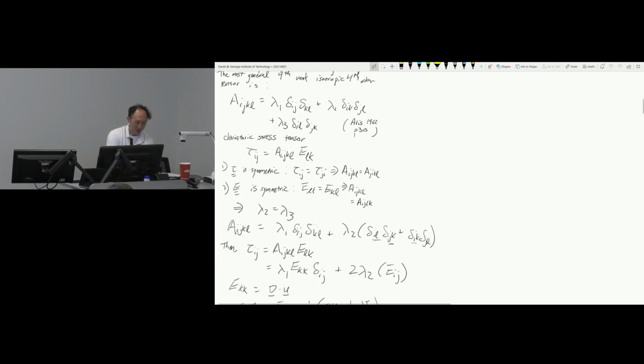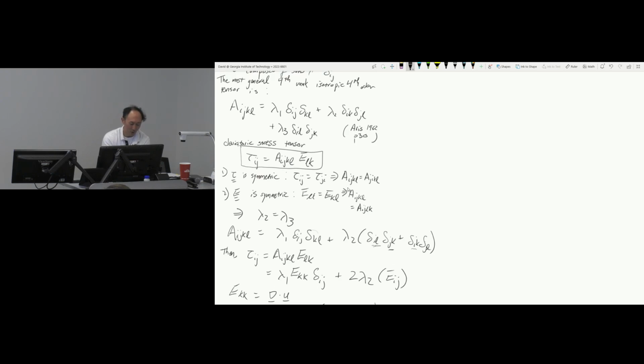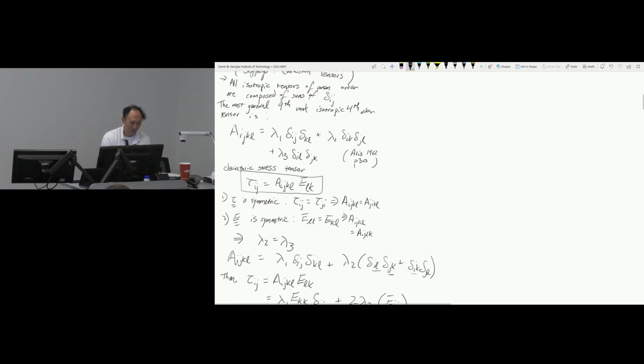We have this deviatoric stress tensor, and we know it's a function of the rate of strain because the rotation, the omega matrix, has no fluid relative motion. Originally it has 81 different parameters, but because it's symmetric, we could reduce those parameters down to just 2. This is isotropic, which means there's no dependence on direction. There's no preferred X or Y or Z.